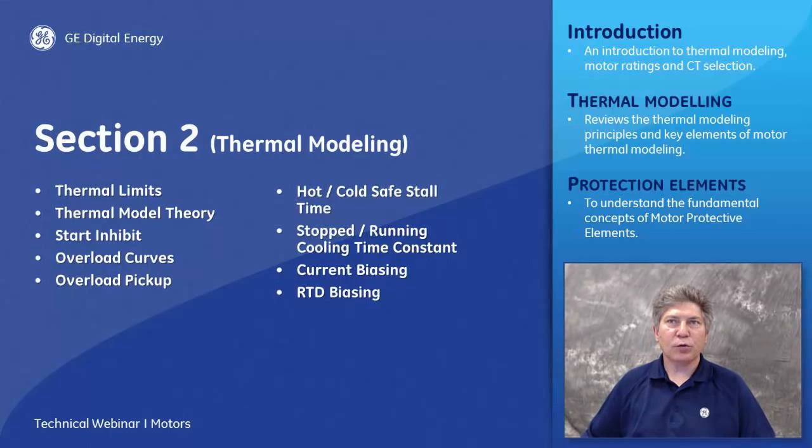In section 2, we will review the key aspects of thermal modeling. We will take a look at the motor thermal limits curve and the information that is provided from the motor manufacturer. We'll review what causes a motor to heat up and how much time we can afford before thermal damage occurs within the motor. What are the overload curves used for? What is the function of the overload pickup level? How long does it take for the motor to cool? Which parameters block us from restarting a motor and why? Let us begin with the section called Thermal Modeling.